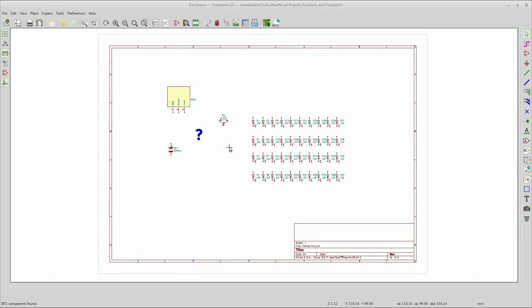I do want to mention how really important it is to get really used to this process, because making your own footprints, maintaining your own libraries and your own symbols is probably, I'd say, critical to you in a company type capacity, or even if you're selling anything. You don't want to be relying on other people's footprints and libraries that come in and out because somebody made a change and it updated from GitHub and then something's maybe not working right. You just don't want to trust it, so you want to do your own thing to rule all that out.